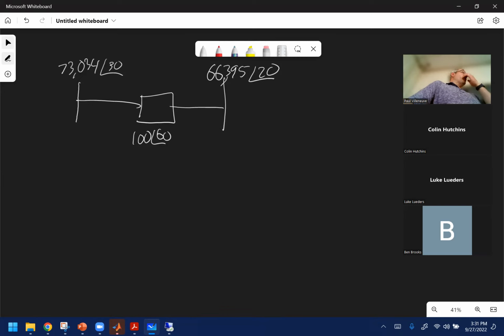If you remember when we talked about it in class, and you can go back to the videos, I said the voltage drop across here is how you can determine the current. So V drop is equal to V bus 1 minus V bus 2.